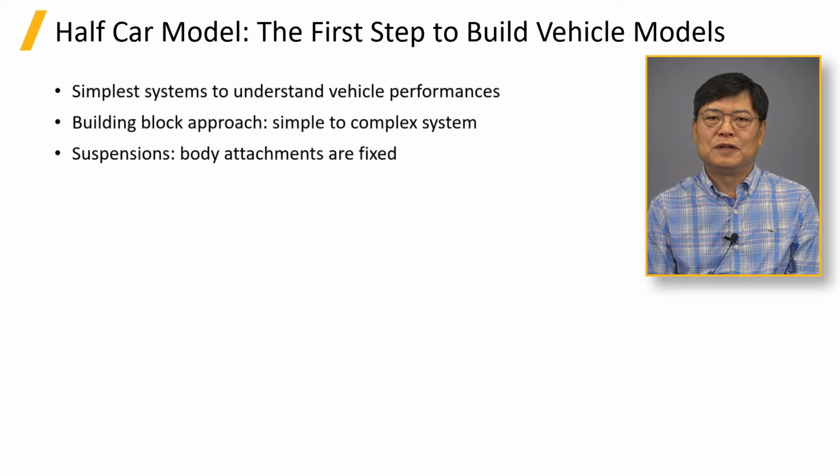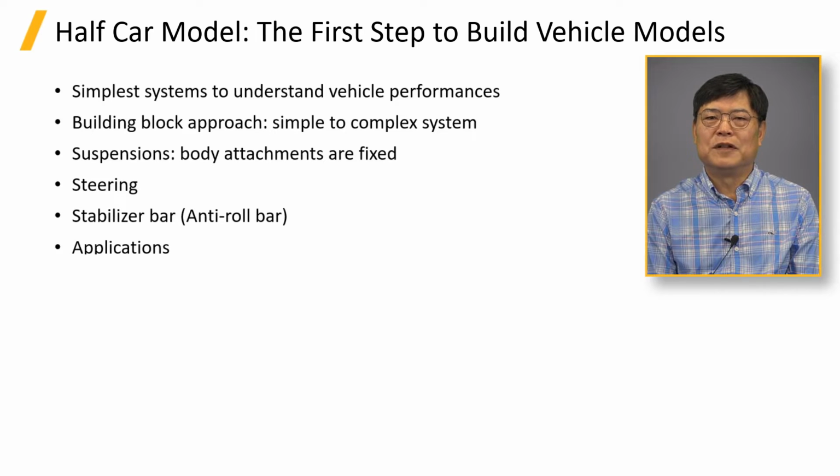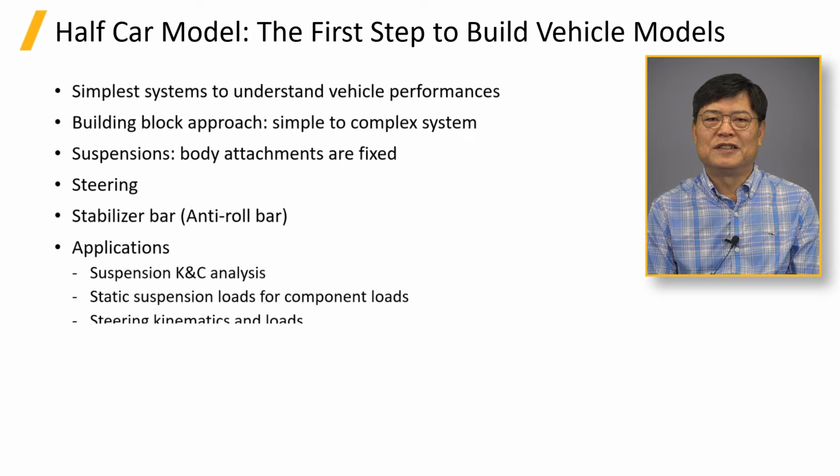In most cases, the half-car model demonstrates the quasi-static behaviors of the suspension. Wheels and tire patch forces generate the suspension kinematics, compliance, and component load. A steering system and a stabilizer bar give more information about steering kinematics, compliance, steering load, and vehicle roll.